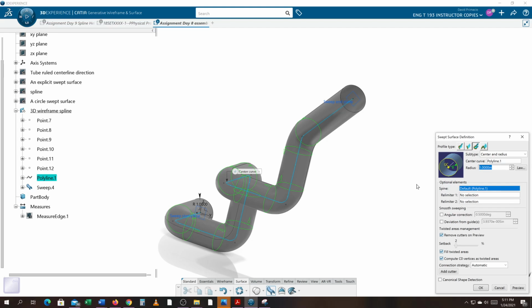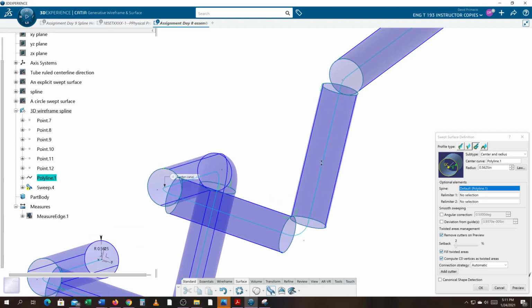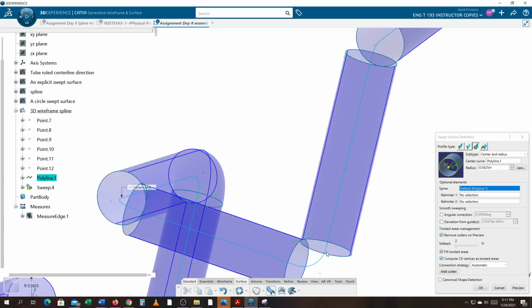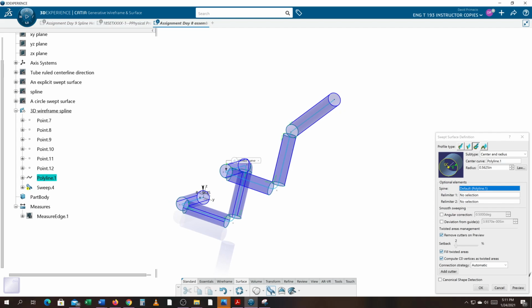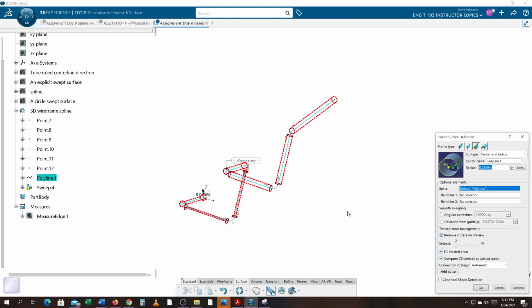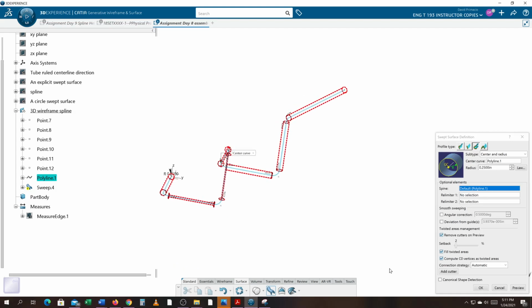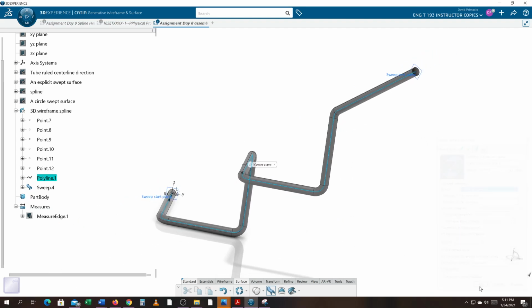Let's go 9 divided by 16 and hit tab and hit preview. Oh, 9 divided by 16. See, they're going to touch because I use 9/16 radius. Let's go 1/4 inch radius. Oh, shoot. I had to hit preview that and select OK.